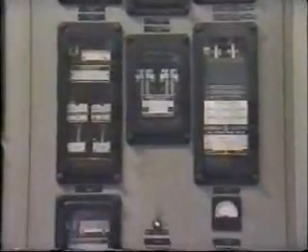When you are working around this equipment in the field, always remember that the remote earth may be at different potential to the station ground. Be careful not to place yourself across these two potentials. So we can see that the simple pilot wire system is not so simple after all.